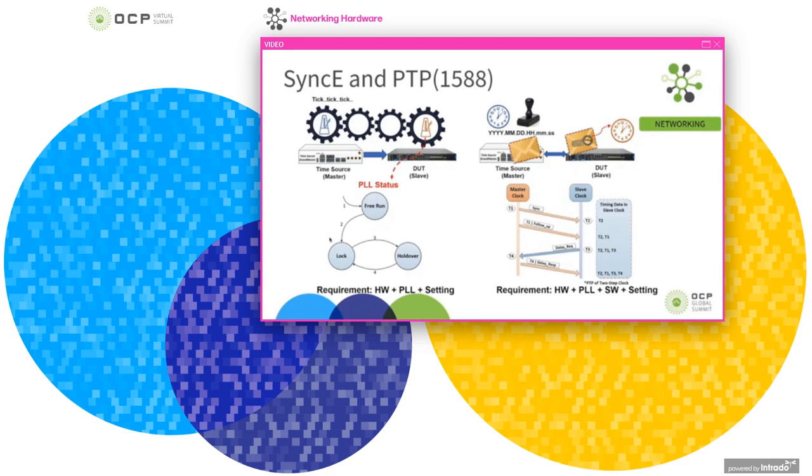So when you need to implement Synchronous Ethernet, you need to make sure the hardware frequency path is working very well, and you also need a PLL inside it. In that SyncE system, if you take away one component, just like taking away a gear here, the rest of the system will lose the frequency reference source. So we need to go through a physical link in order to achieve frequency sync.